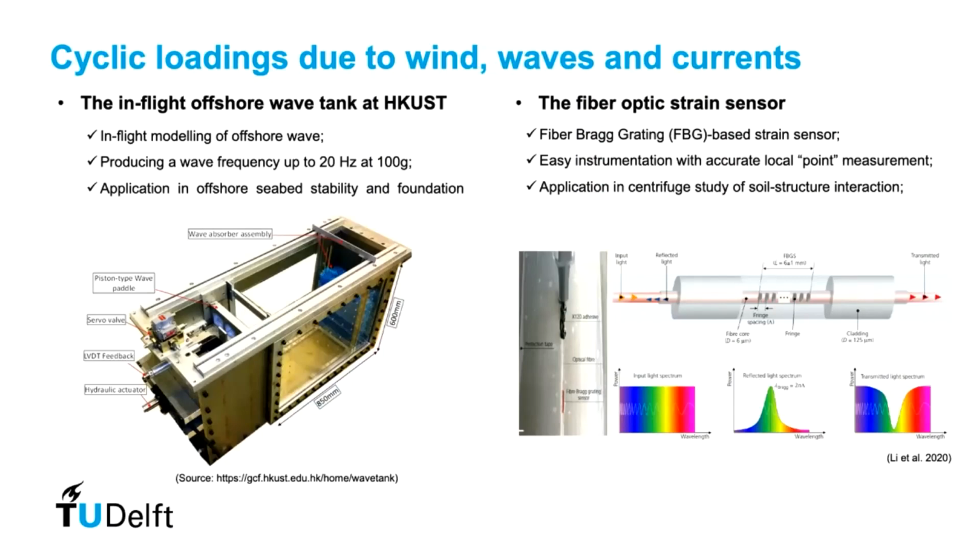If you process or interpret that behavior properly, you can then identify the proper location for those strains. And if you understand or assume some mechanical behavior in your structural element, you can even tell the forces acting on it. So these fiber optics are used for several purposes, for displacements, for pressures, and certainly more to come in the near future.